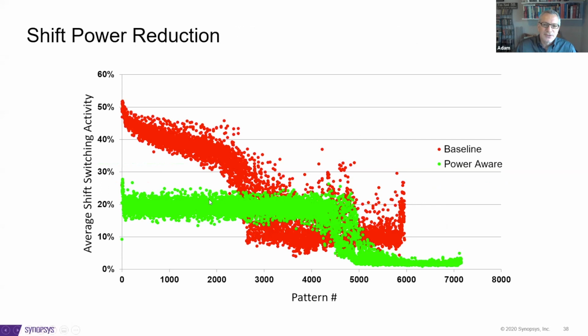And you can see the results here without any shift switching ATPG mitigation techniques. You get a bunch of switching typically at the beginning, and then it tails off into something more manageable. On the other hand, if you can actively stop the switching activity during the shift operation by just scanning in less changing data shift to shift, then you can get some reasonable switching activity.